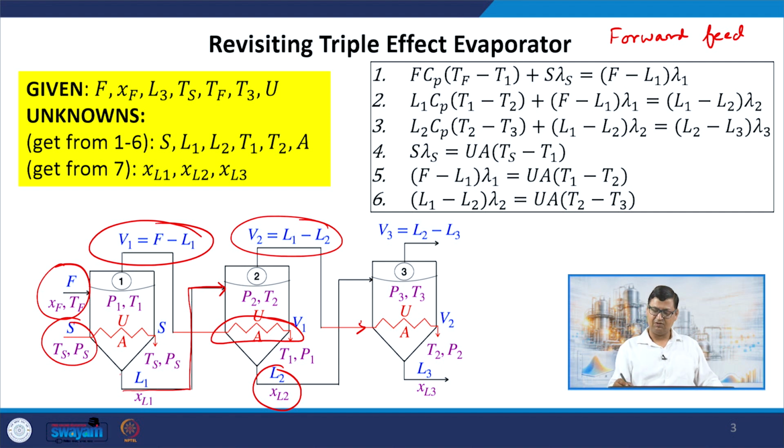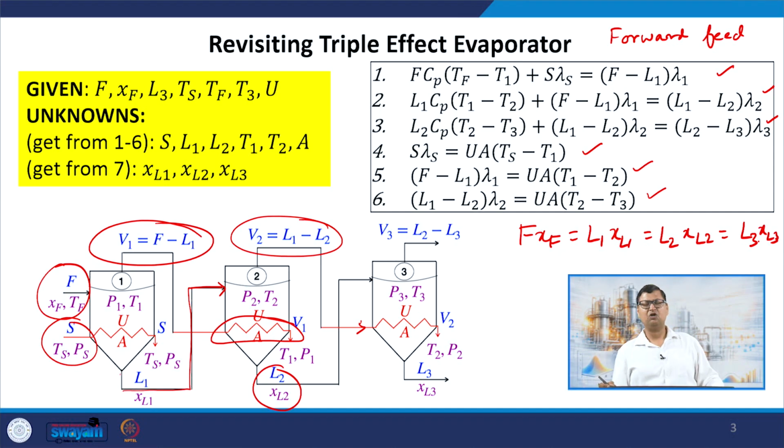Based on that, we have three energy balance equations for this system and three heat exchange equations. We also had solute balance equations like this, but since the solute mole fractions do not appear in any other equations, we can take them separately and solve them after we have solved for the remaining variables. So we have chosen a particular choice of unknowns as L1, L2, T1, T2, A, and for this case we will develop the